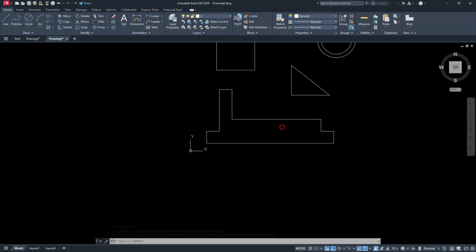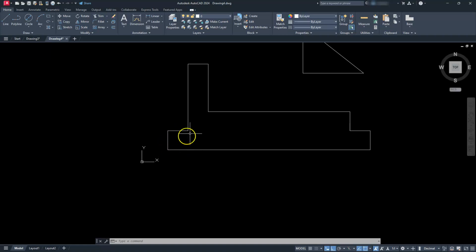And I just now saw down here at the bottom that these actually should be at angles, right? Now, I did join this together, so I could select it and explode it, which is going to be this icon here. Go ahead and draw a line going from that endpoint to here. Likewise on this other side. And then you can go ahead and erase this. Now, I could have kept those squared off as well and fixed that when I made the 3D solid. But in this case, I'm just going to do this in as few steps as I possibly can.